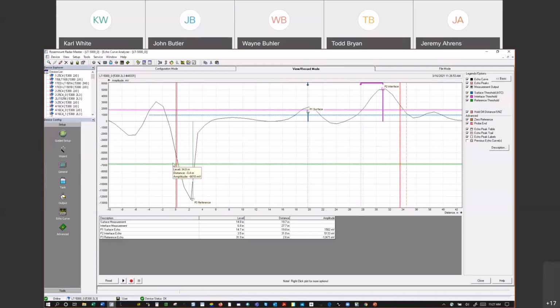I just realized we hadn't covered that at all. Sometimes we need that. Yeah, like I say, normally not so much. Normally we're concerned with the reference pulse, like you mentioned, which should be at 0. Threshold, amplitude, stuff like that usually falls between the 0 and the bottom of the tank. That's all we're concerned with. Anything to the right of it, we're not reading. Anything to the left of it, it really doesn't matter unless there's a problem.